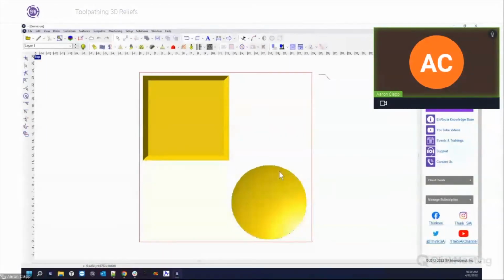I need that profile back. I created this with this profile, and I told it to create the profile with the exact dimensions as this. So if I bring up my F2 menu, I can see that the width is 1.5737. So that's how wide this profile is.